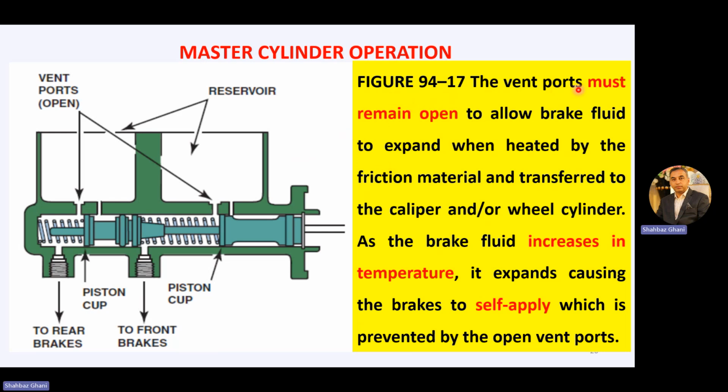The vent ports must remain open to allow brake fluid to expand when heated by the friction material and transferred to the caliper and or wheel cylinder. As the brake fluid increases in temperature, it expands, causing the brakes to self-apply, which is prevented by the open vent ports. In normal condition, we have these vent ports here, and these are your replenishing ports.